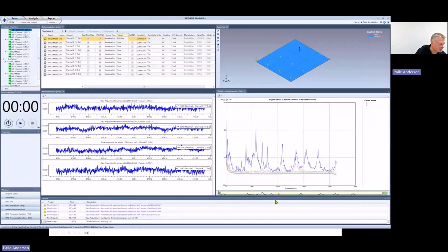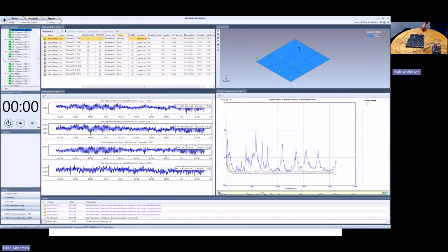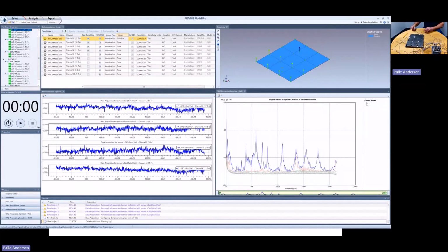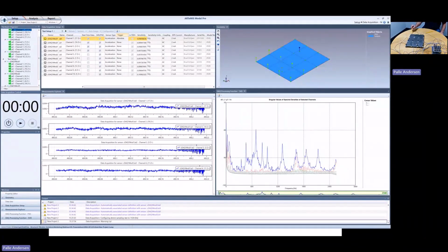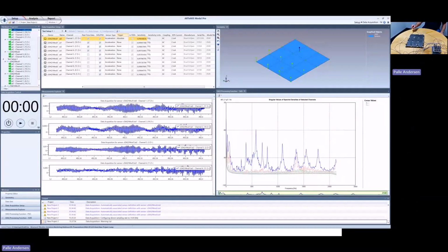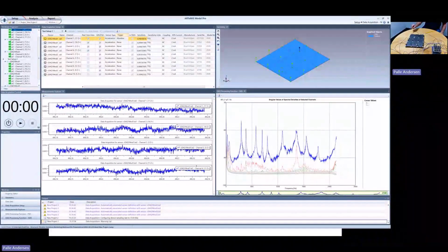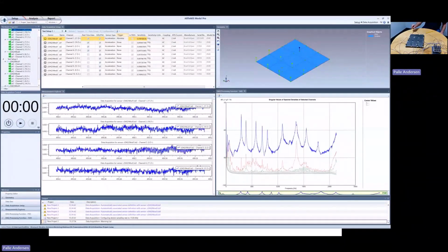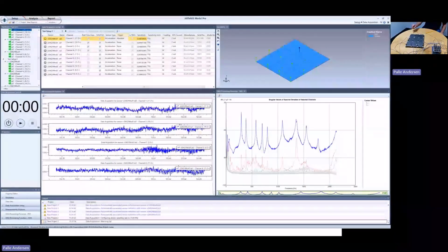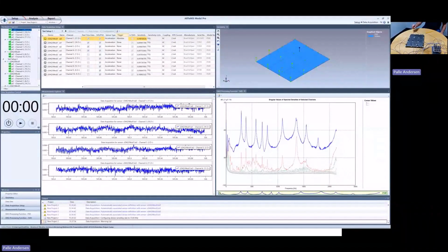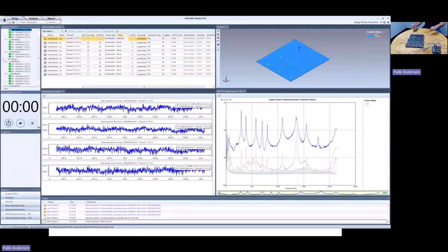Now I'll switch my camera back to the other one so you can see what I'm doing here. Because if I now try to take a pencil here, and now I will just hit this point here. I can hit it. Now you can actually see that the blue line is growing up now. It's becoming quite significant compared to the other ones, indicating that there is a single input that is exciting this structure here now.